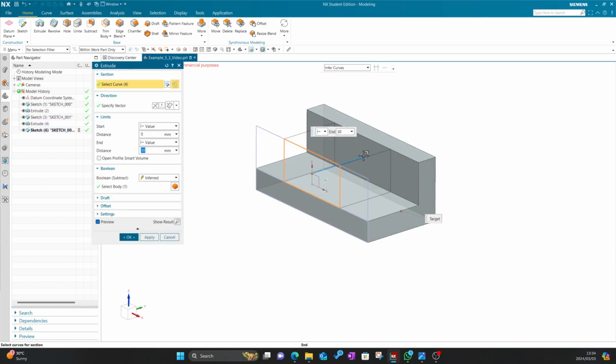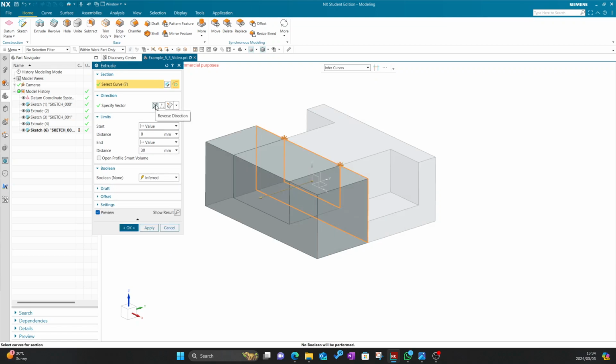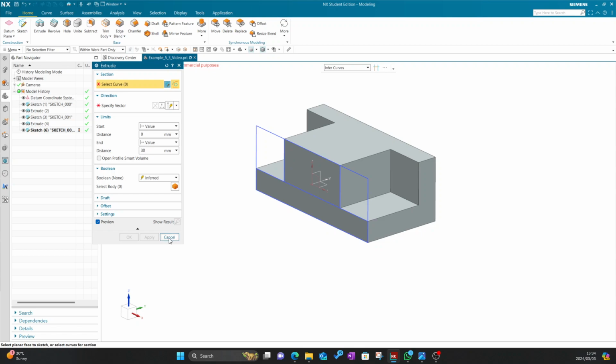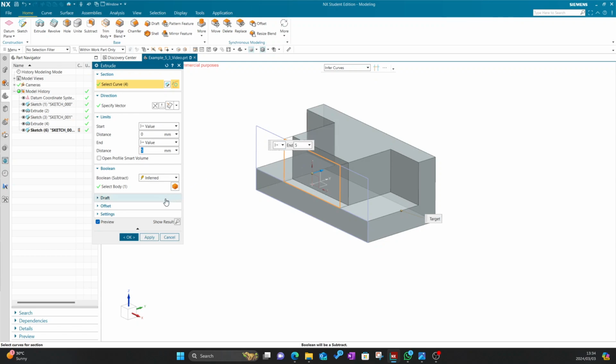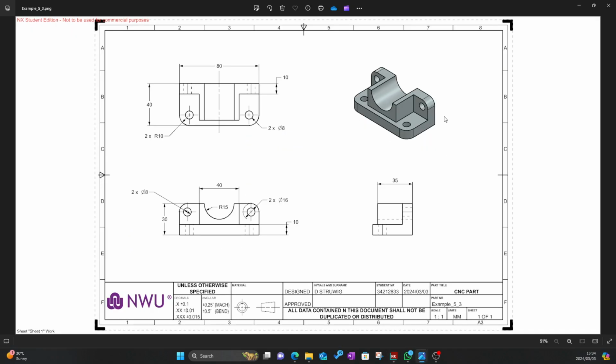So you can either double click on that end and then it will reverse the direction, or you can click on reverse direction. I'm not sure what it did now. Let me just create another extrude from that sketch. So that's 5 millimeters and to the other direction, and we use the invert, so it will automatically detect that I want to subtract that. So clicking OK. So now you'll see that we're getting closer to this figure or representation. So we can now add this half circle cylinder.